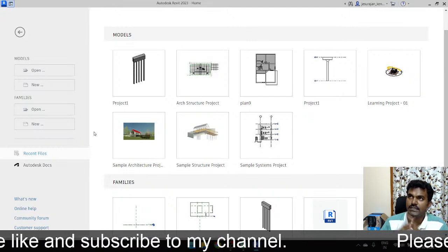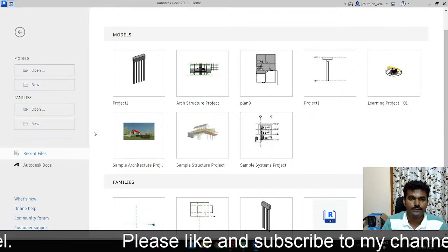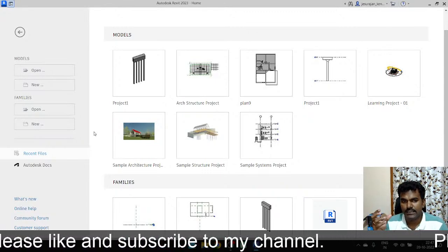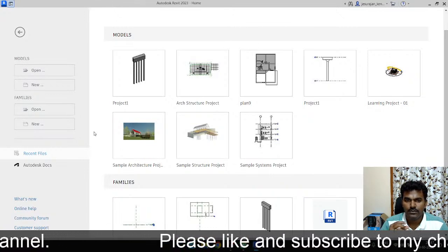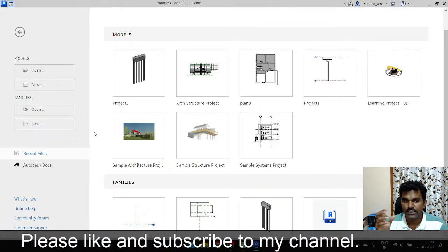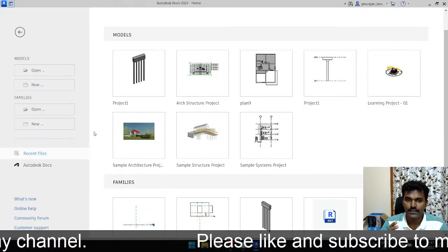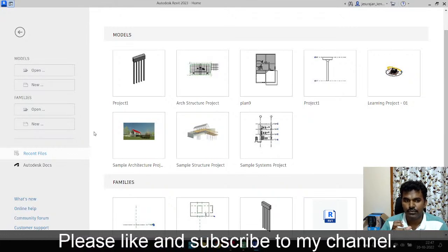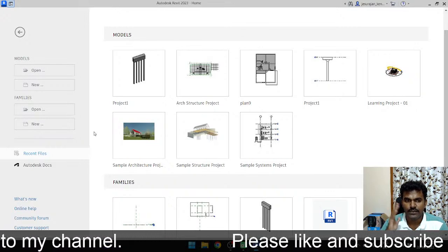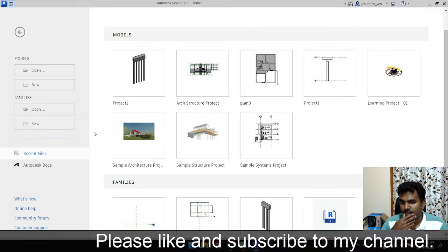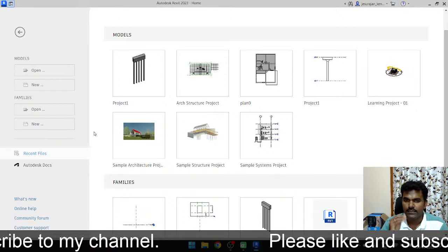Now I am going to create a window panel. Let's draw a window panel. I'm going to attach this handle to the window panel. We should understand that we are using the handle as a nested family in the panel, and the panel is also nested in the main window family. That's my logic, that's a way of doing a window family. I think that can help me create more styles with similar windows.